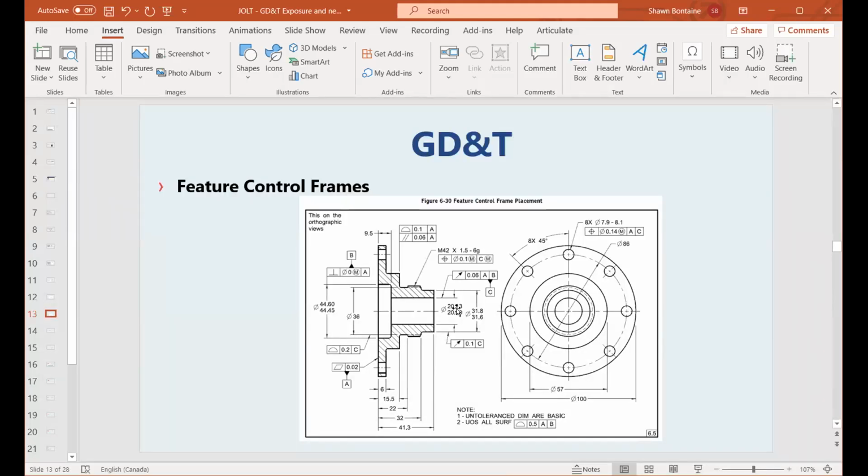You can also communicate or come across feature control frames. The third method is by bringing an extension line up from the actual surface where it appears as an edge or a line, and then you can attach the actual feature control frame to that extension. The fourth common method is by making an extension of the physical dimension and attaching the feature control frame to an extension of that dimension. So not only are we controlling the diameter and we're controlling the depth, but we also have a perpendicularity requirement to datum A in order to establish this feature as datum B.